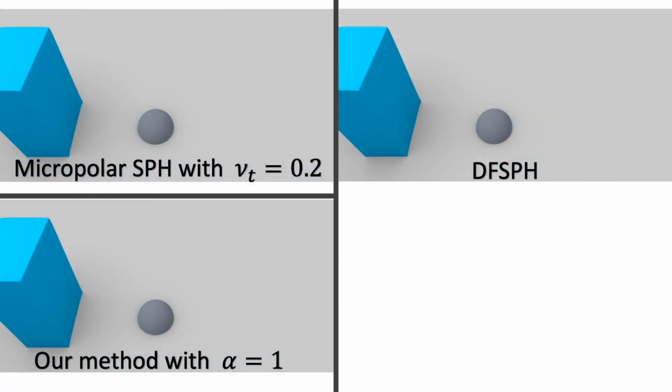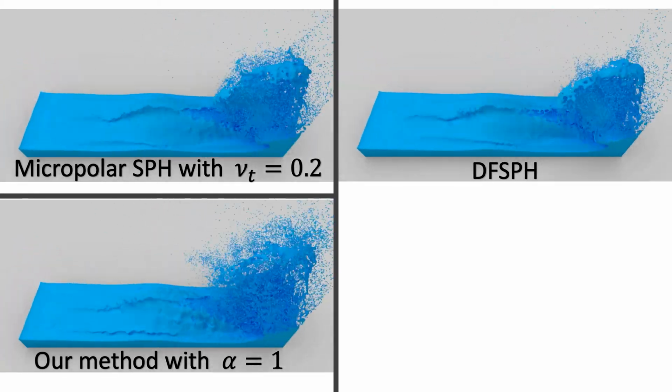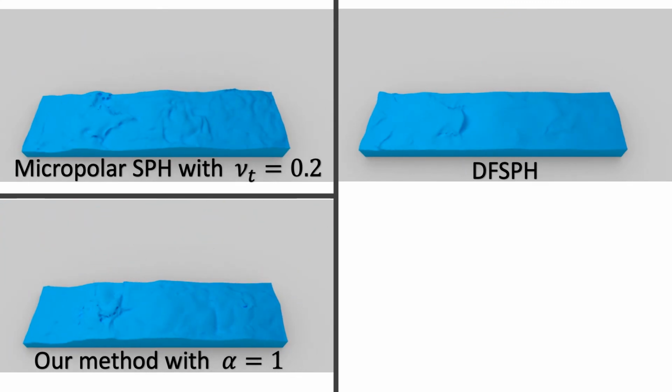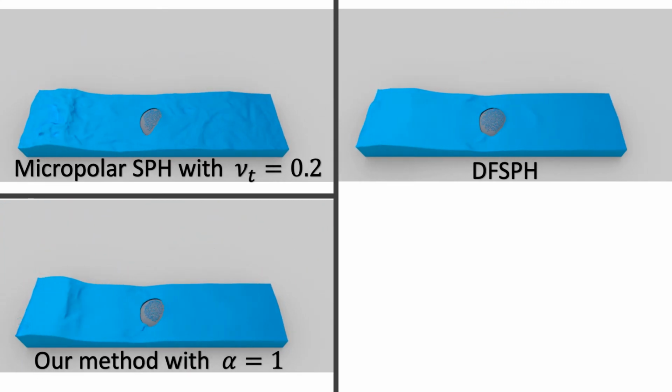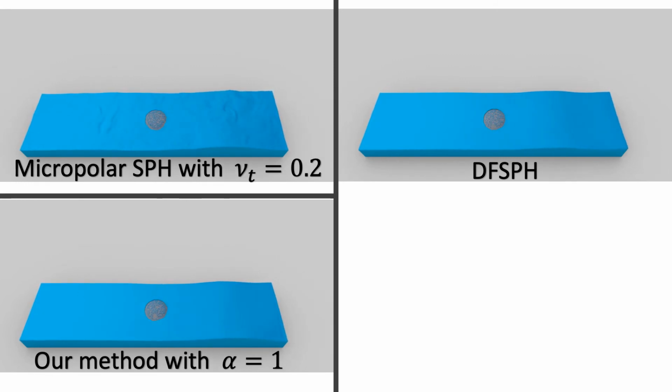In the next experiment, we show how both methods would handle a closed energy system. A hemisphere obstacle is flushed with a fixed volume of fluid. This means only limited kinetic energy is involved in this scenario. Both methods can increase the turbulence performance, but our result is more pronounced than the MP's. What's more, our method can remain calm after the energy is totally dissipated due to the viscosity, like the traditional SPH. But the MP solver tends to constantly generate excessive energy, making the fluid hard to restore to calm again.